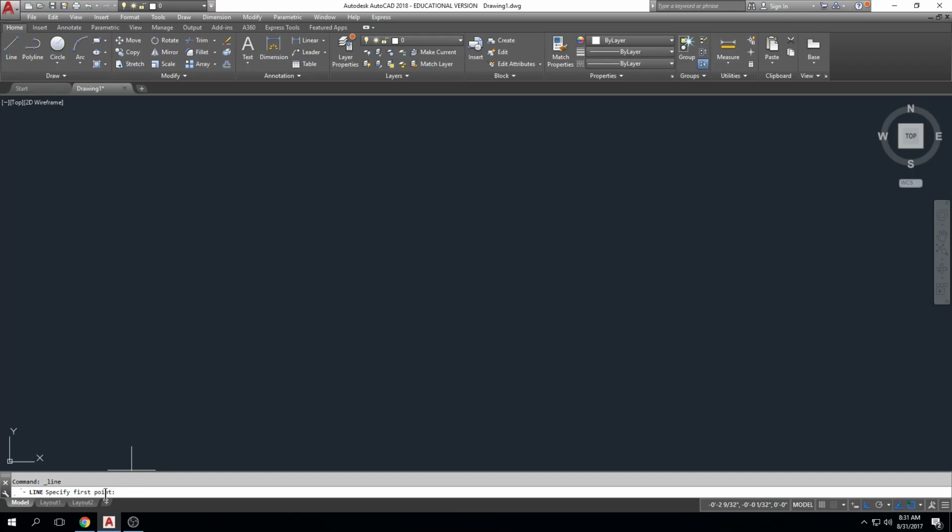So it's giving me instructions on what to do next. And that is going to be very typical of AutoCAD. You initiate a command, you look at the command line, it tells you what's going to happen next. Okay? So if you get lost in a command, you don't quite know what to do, initiate, then look at the command line. Now, the command line can also be at your cursor, right? So some instruction could pop up at the cursor if you're using dynamic input.